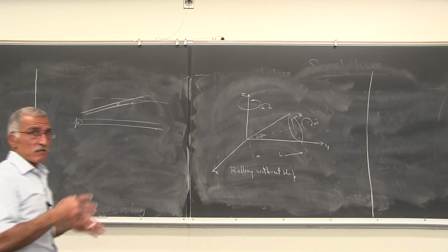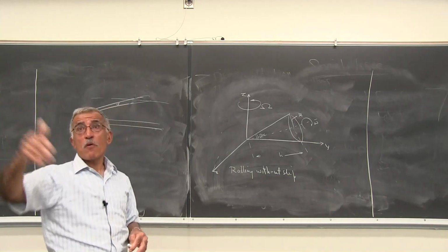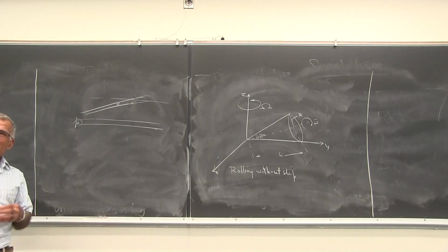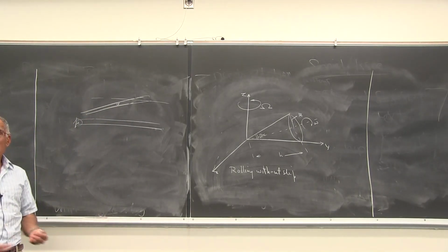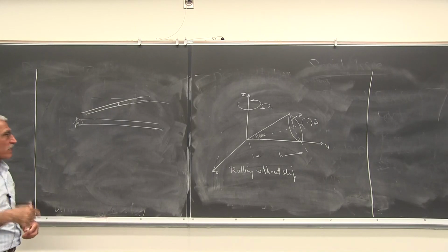Because if we know it, then we can see the displacement at every other point. So you have to find the axis with respect to which the structure is rotating, which has all zero velocity. Every other point has the same angle, but this is a point that has no velocity. So you have to identify it.